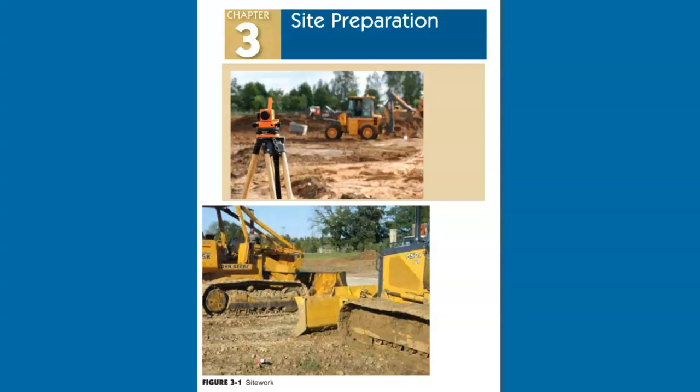Site preparation. In preparation for constructing buildings on a property, the builder must consider a number of factors related to code requirements. The buildings must be located according to the approved site plan to meet the requirements of the International Residential Code (IRC) and any applicable local ordinances. The soil must be suitable for the support of the building and is factored into the design of the foundations. And the building must be elevated sufficiently and the site graded to provide surface drainage away from the building.